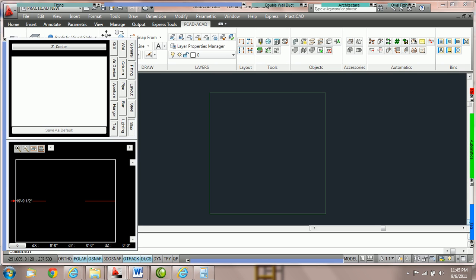Now we're going to want to put objects on the drawing above this slab. Let's say it's at the 3rd floor. And we're going to want to reference all of our elevation tags from the duct we place above it, from the slab below it. So we're going to reference it to the floor. However, we want to make sure that when we export this drawing, that duct, if we put it 10 feet above a 20-foot high slab, the duct should be 30 foot in the BIM model.